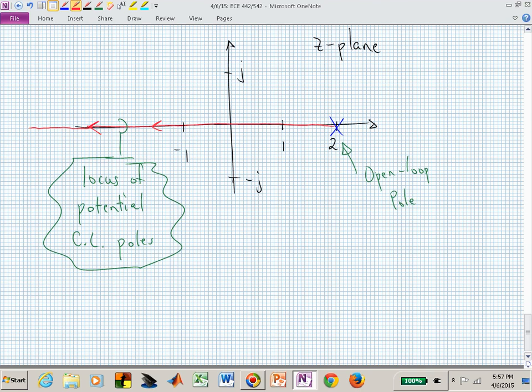Do you see the sweet spot? The nice location or segment on the real line that you would like to have K between, or that governs K? As you crank up this knob, K going from 0 up to infinity, you're going to reach a value where K reaches z equal to 1.